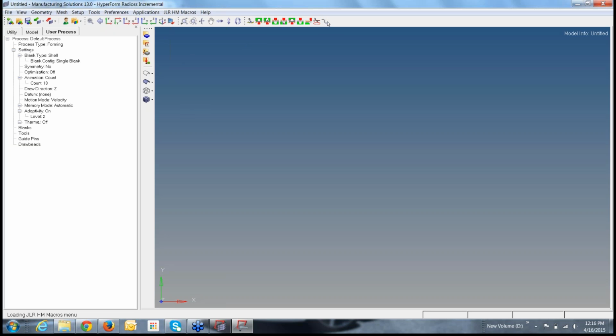Along with that you have the auto process buttons. These are called auto process buttons. This will help you to set up the gravity, single acting draw, single acting with support, double acting, flanging, trimming and spring back. Trimming is a pre-processing activity, hence it will not require any solver as such. You just use the trim line and delete the elements either inside or outside the formed blank.